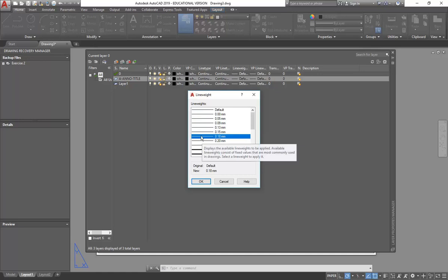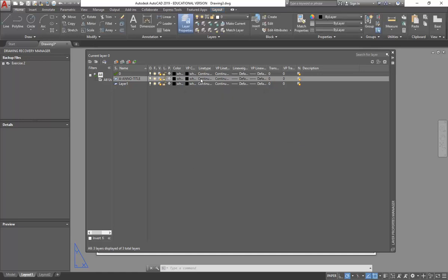I'm going to go for 0.18 to start with, and we'll maybe look at adjusting that. Does the scale make a difference to what line size you can use? The line weights, do you mean? It makes a little bit of a difference, but for title blocks, you probably would want them the same. But you're right in a way. Line weights do vary depending on scale, but we'll get more into that later with details.